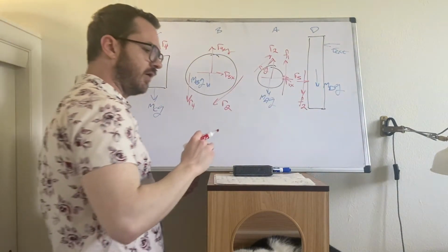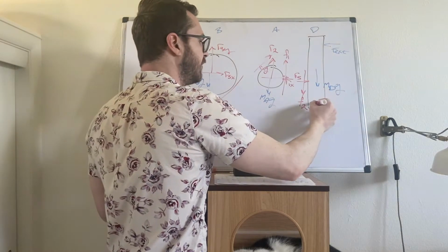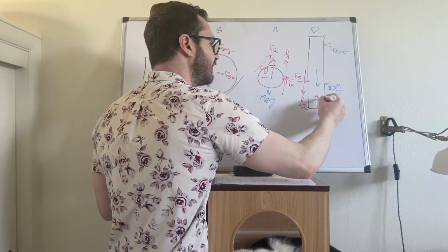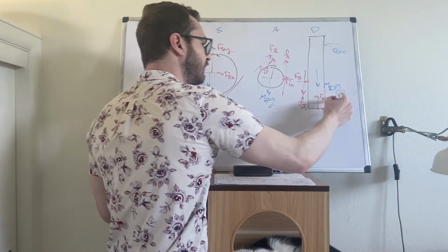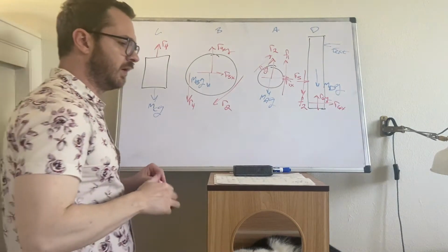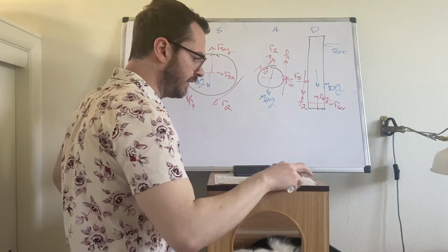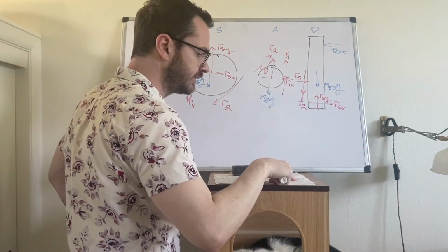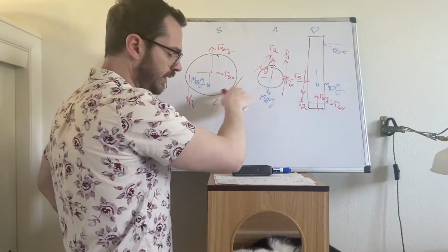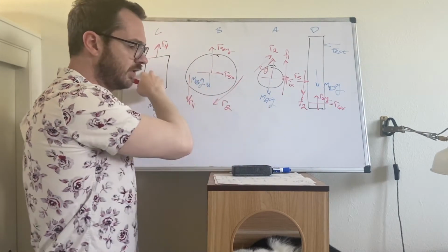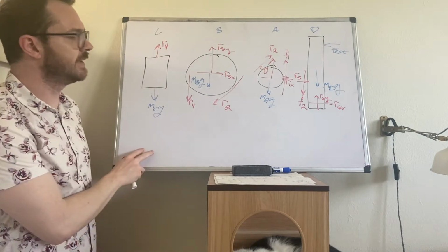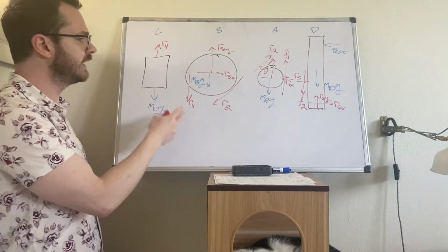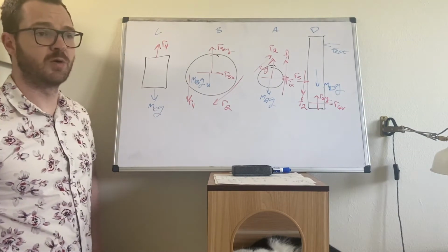Okay, and then also acting on the handbrake, remember, the handbrake is pinned on bottom, so there is a set of reaction forces here as well. This one is R6X, R6Y. There we are. Okay, I think that's it. Gravity, we got R5 included, and the friction, good. We have reactions at the pins. Good. Okay, keep these in your notes. I'm going to erase these, and then one at a time, we'll go back and do each one of these bodies, sum of forces and moments.